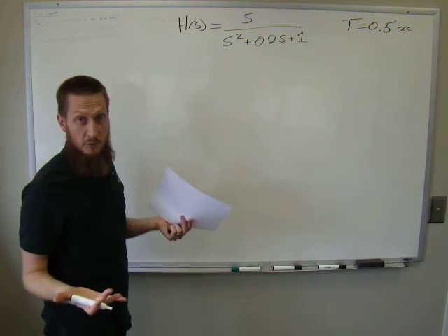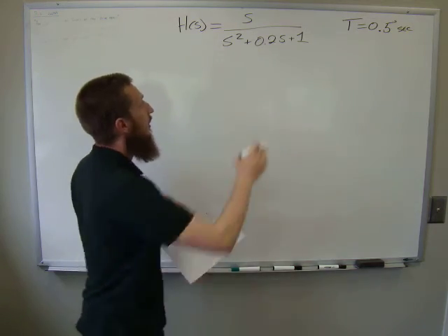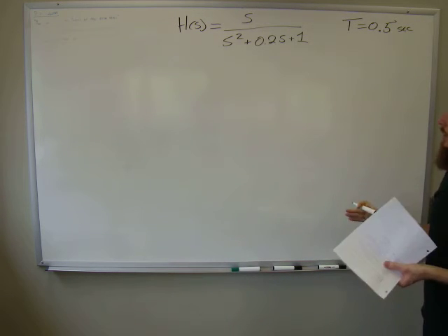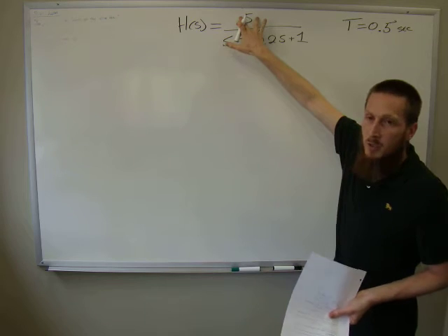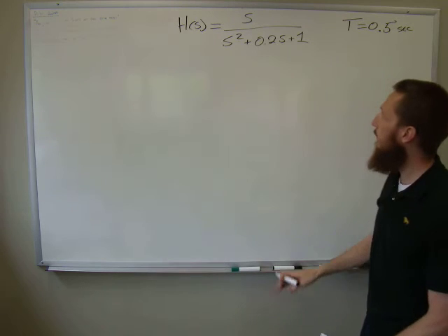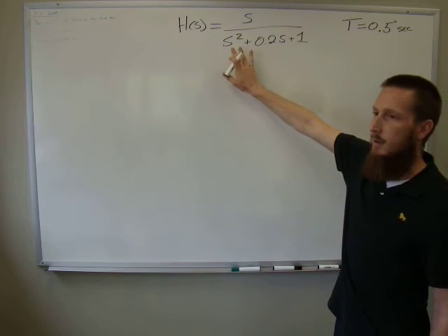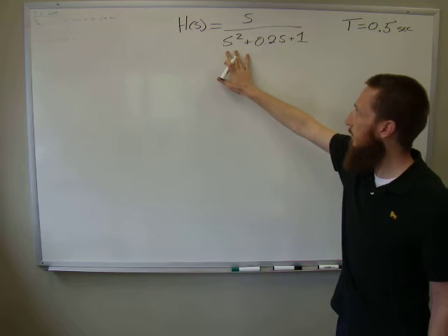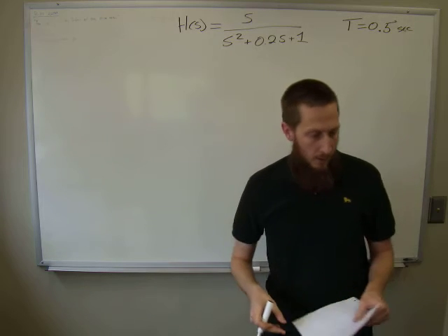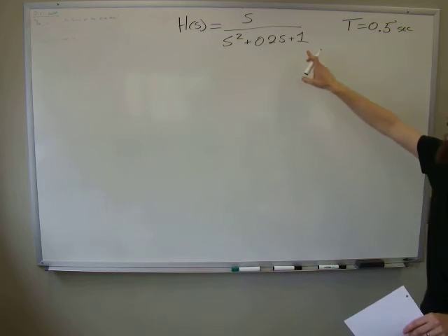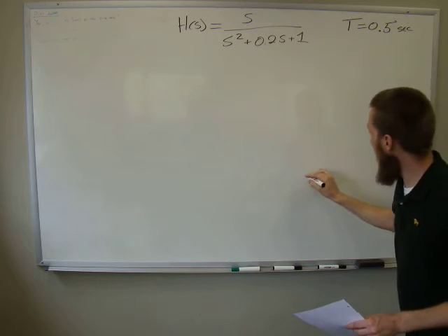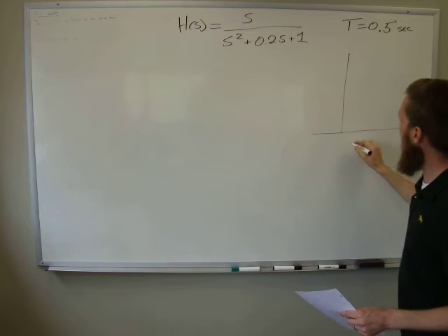What type of filter is this? Second order on the denominator. We have an s in the numerator. From our knowledge of Bode plots, we can look at this and say, okay, this is a positive 20 dB per decade, starting at omega is equal to 1, and it goes forever in both directions. This is a negative slope of negative 40 dB per decade that starts at omega n, and omega n is at, let's see, this is omega n squared. Is that right?